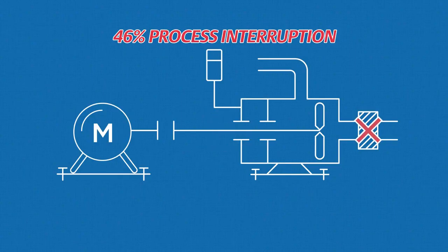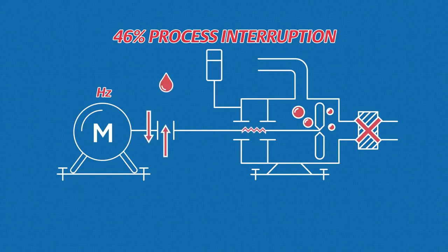A clogged filter bringing a pressure drop at the inlet of a pump will induce cavitation, which may cause vibration and degradation of the bearings. Electrical, lubrication, coupling faults, leakage of internal or external products on your seals are among the causes of accidents with serious consequences for the safety of your facility, your personnel and the environment.